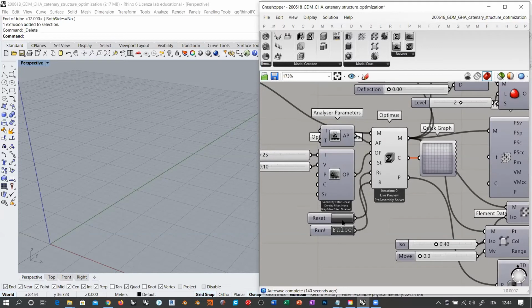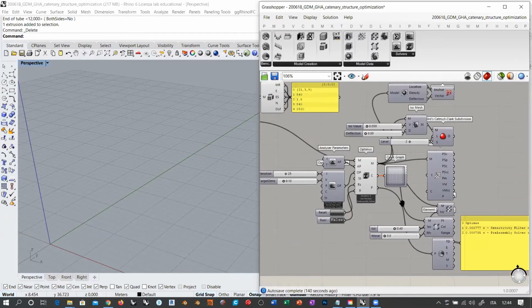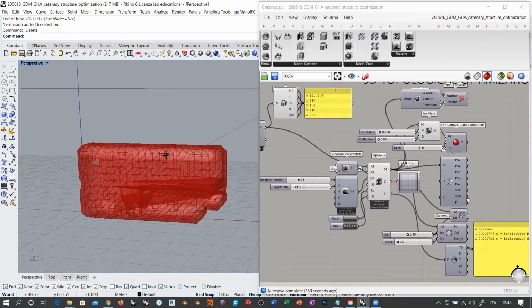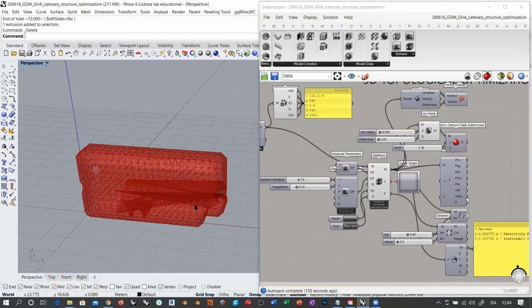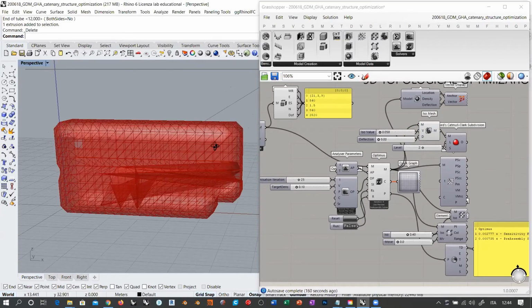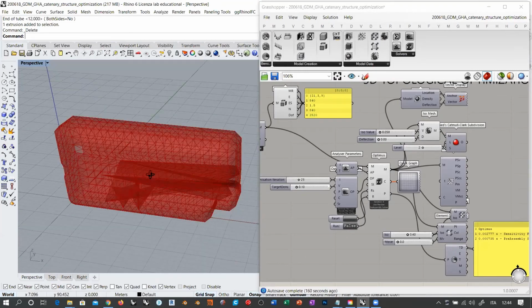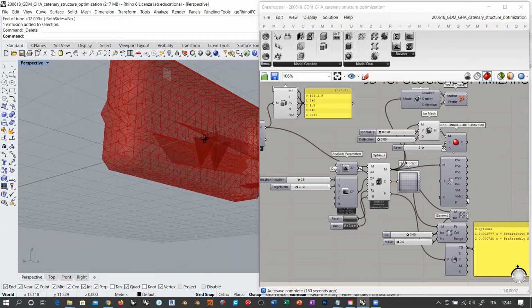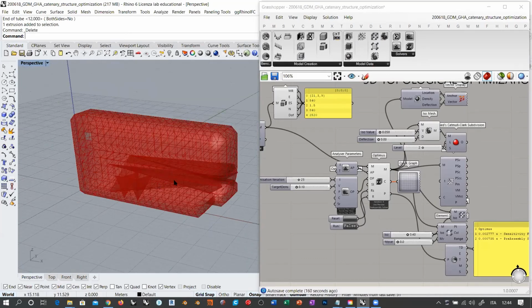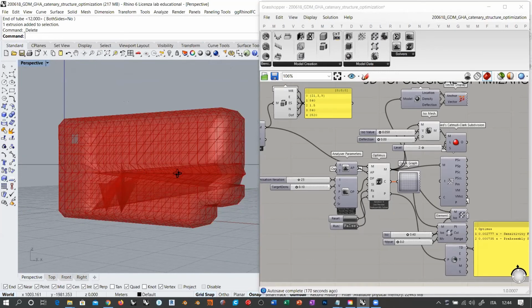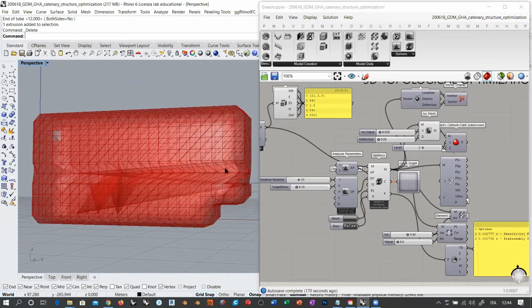So everything is ready. There are many outputs here, as you can see. I want to concentrate a little on the mesh output. Initially, you see this is quite a weird mesh, but it doesn't matter because it's going to get optimized. It also misses a quad here, or two triangles. And there are some self-intersecting vertices that are very bad to observe. But anyway, once you start running the simulation, these things will disappear. So don't worry about this.